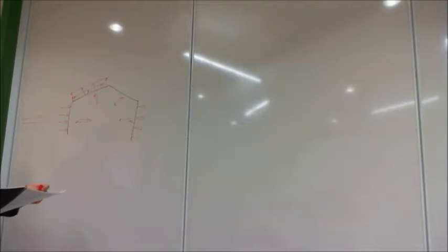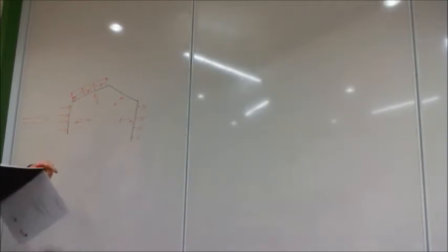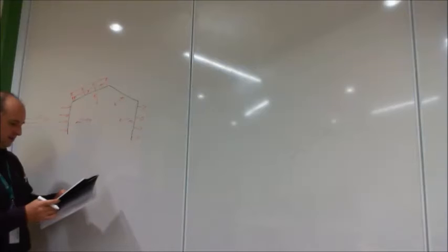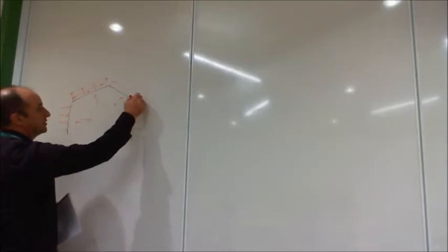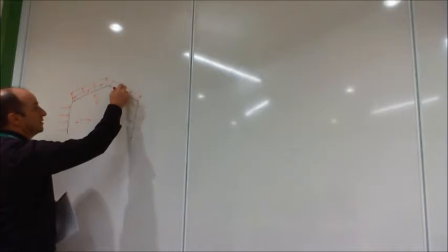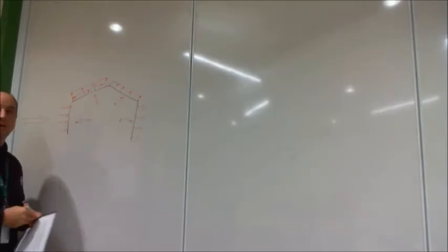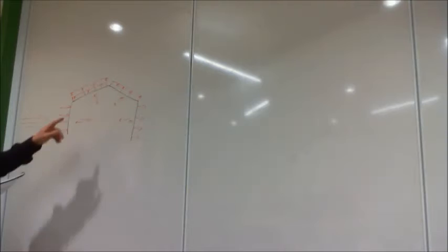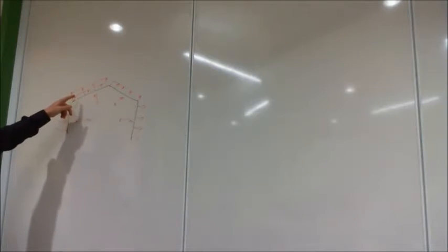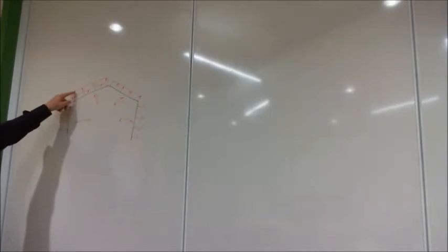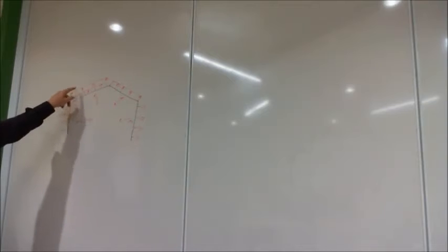And on the downwind side, it can either be the same if it's a flat roof, or if it's got a bit of a slope on it, it's going to be generally an uplift. On the downwind, sometimes you only get one value, which is nice. Okay. So, on the upwind side, say for a roof which is at 10 degrees, that might be 0.9 or 0.4. And you've got to say, why are there two different values?